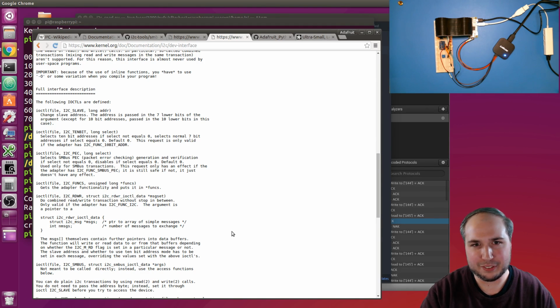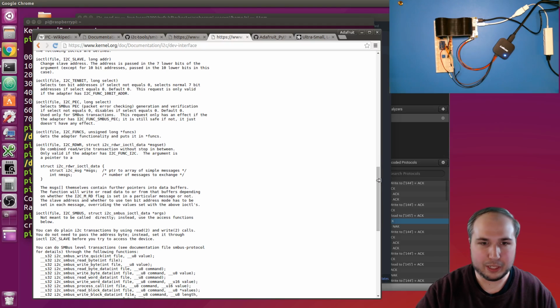It's almost like calling a custom function. So a device driver, like the I2C driver, can say, okay, I'm going to expose a character device you can read and write to, but I'm also going to expose some extra functions that you might want to call. And you do that using this I/O control function. And I won't go too deep in the details here, but using this, you can actually do things like construct an I2C transaction that says, okay, I want to write a byte of data, and then I want to read a few bytes of data back.